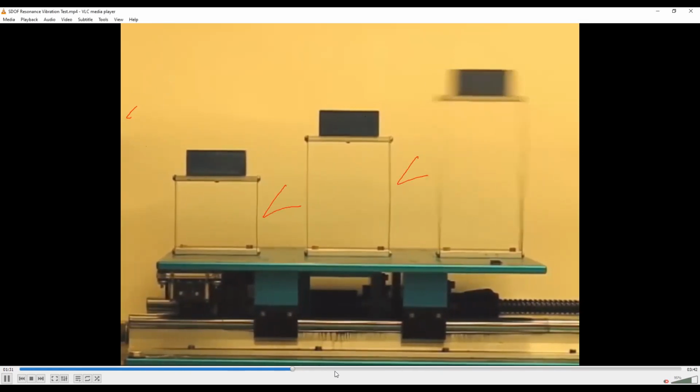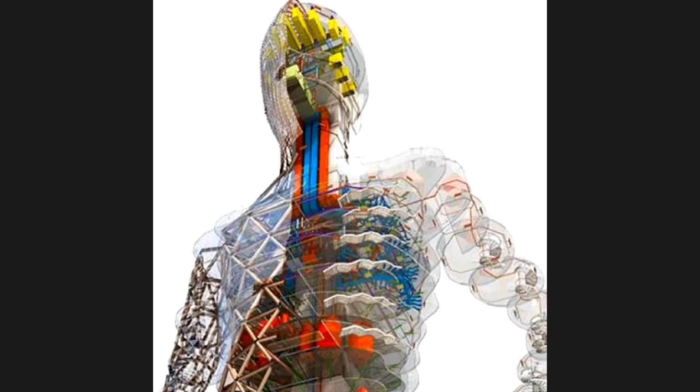Now again the frequency is increasing, and in the last, when the frequency is so high, then your high rise structure is stable and the low rise structure gets affected. So that's why in the modal analysis we are checking the structure response, the vibration, and where we have to apply the exact criteria in the structure, so we can make the structure more stable.